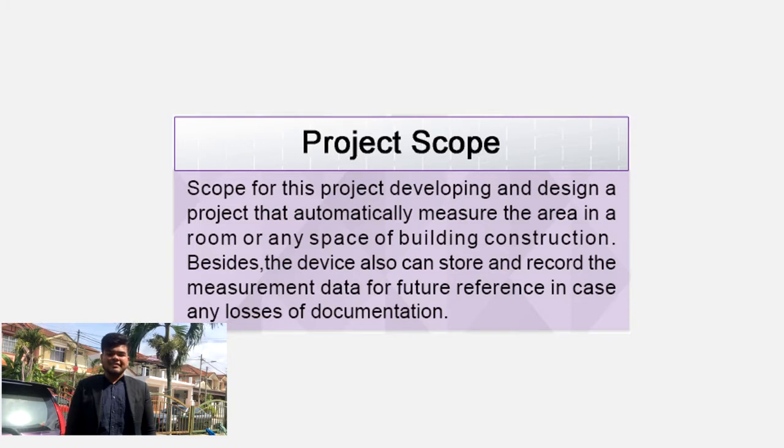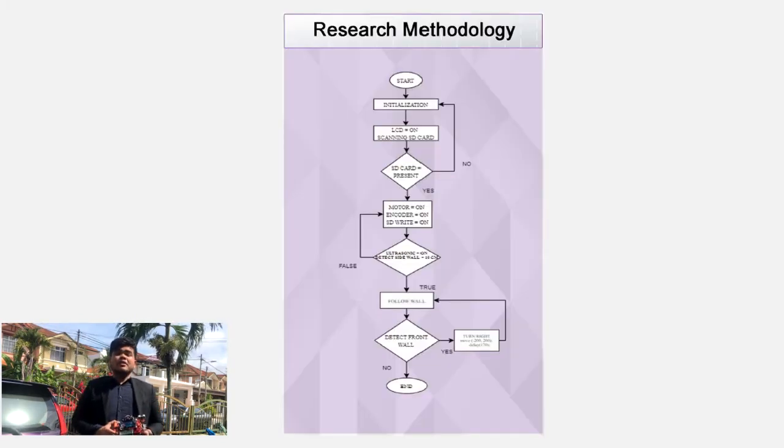Besides, the device can also store and record the measurement data for future reference in case of any loss of documentation. The flowchart of the project: when you turn on the supply, it will power the LCD display showing the initialization of the project, and it will scan for the presence of the SD card. If the SD card is not present, the project will not start up.